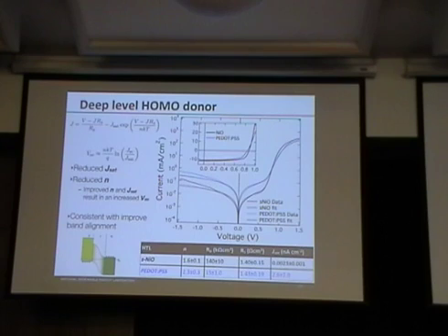So yeah, n is the ideality, the diode ideality. I'm sorry, it's up here. So why is it okay for our ideality factor to be bigger than 2? Is it okay? Wait, I'm sorry. I thought if the ideality factor is close to 2, you have trap-limited transport, that kind of thing. And it's somewhere between 1.5 and 2.5, bimolecular recombination. Like you could tell from the ideality factor whether it's bimolecular recombination or traps. So if the ideality factor is closer to 2, then it looks more like bimolecular recombination versus not.